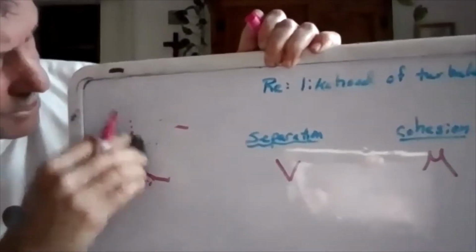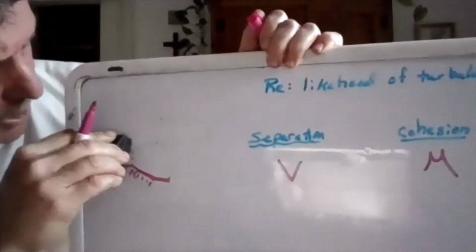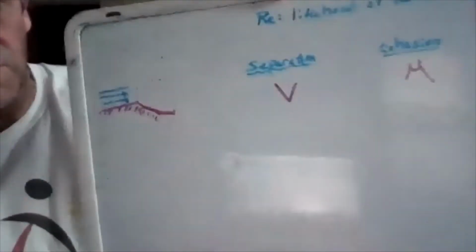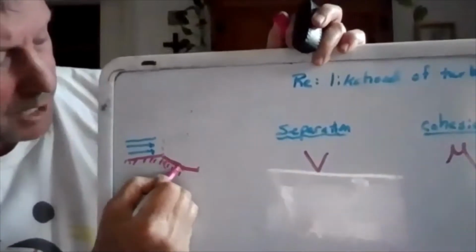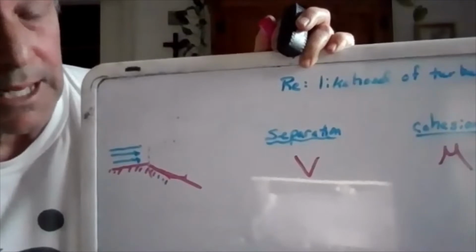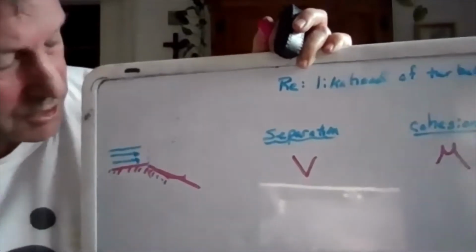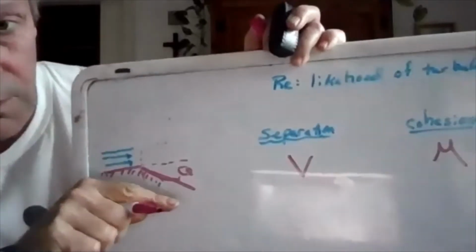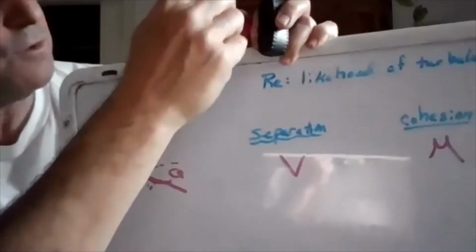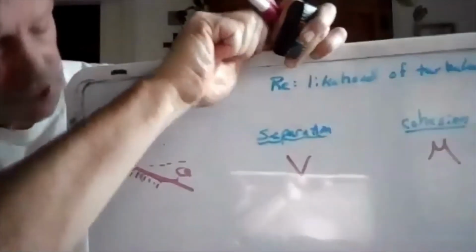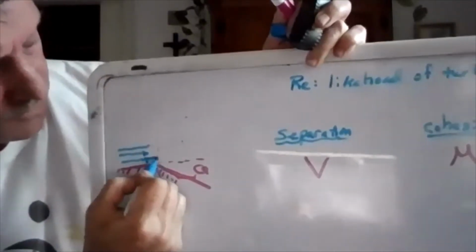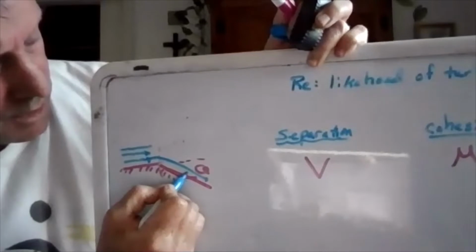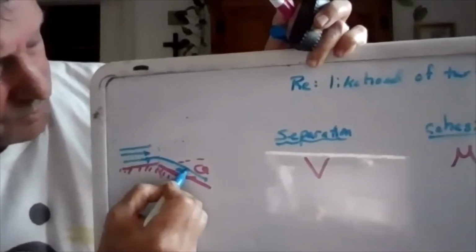So we're just taking a look at the bottom portion of the fluid, all right? So we've got the bottom of the fluid, this fluid is going along, and then the pipe wall actually deviates. Well, what might make it likely that we end up getting separation in that case? Part of it would just have to do with this angle right here. The sharper this angle, the more this fluid has to turn in order to hug this wall.